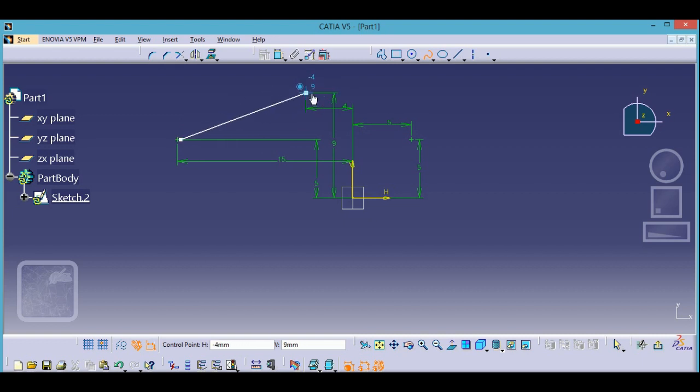After that this will lock, and just select it again. So you can see that an error will happen here. This curve will not be constrained. Okay, just draw it again. Again, just select it, then select it, and then that thing happens. This can be removed by a constraint also, but I'm showing you the direct way of drawing it.